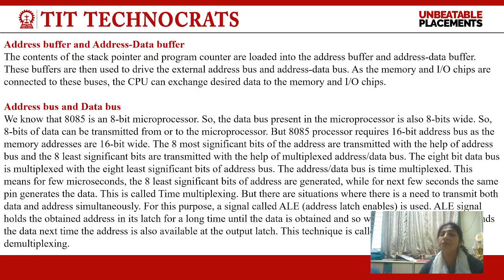The address and data bus is time multiplexed. This means that for a few microseconds, the 8 least significant bits of address are generated, while in the next few microseconds the same pins carry the data. So they are time multiplexed for a very small time. The least significant address bus is multiplexed with the data, and after a few microseconds the data bus is free to fetch or read the data.